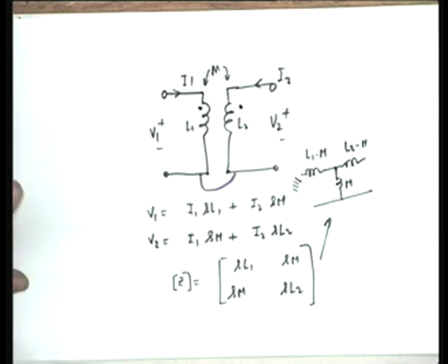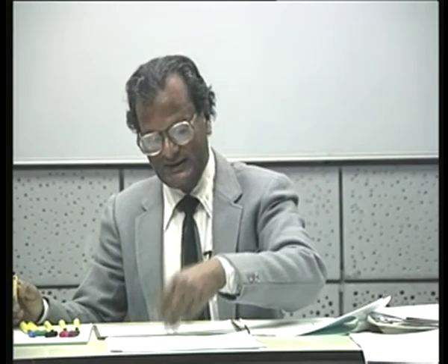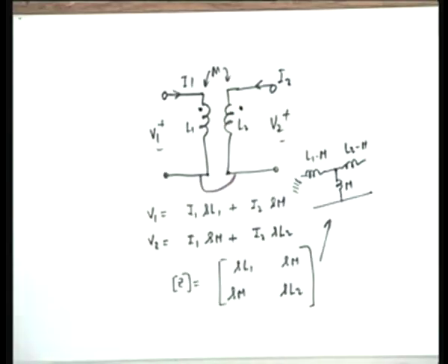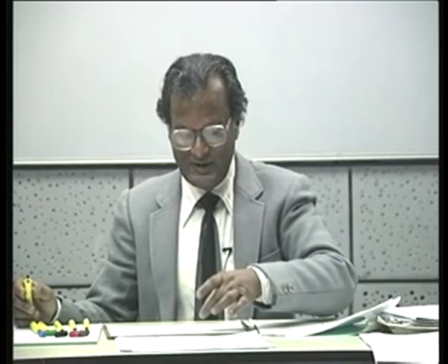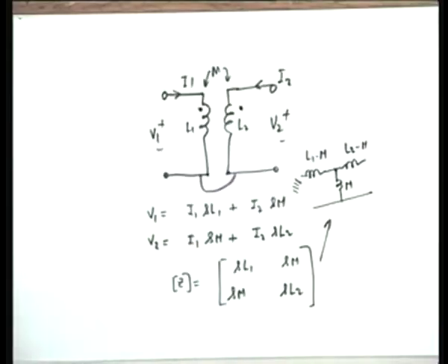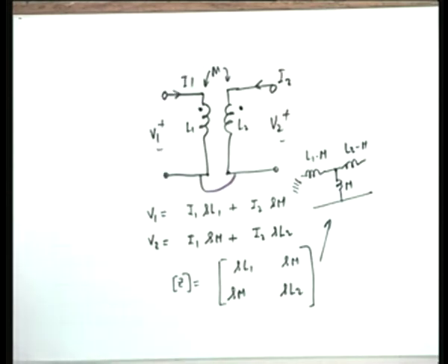Okay. Z parameter was simple. How about the Y parameter? If this connection was not there, can we not tabulate it? We can, because then physically this is not the same as this, but mathematically we can. Mathematically is okay, so long as you work with only V1, I1 and V2, I2. But suppose this is a down conversion, 220 kilovolt to 230 volt, at a substation.